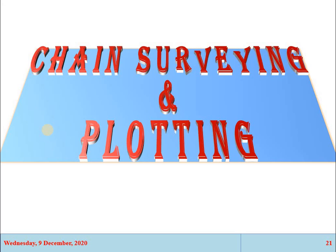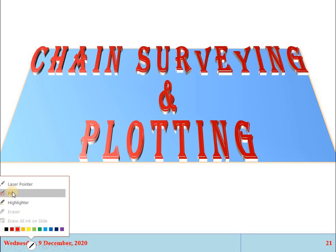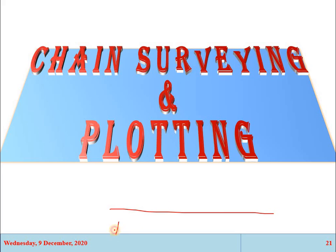In the previous lecture and in practical number 2, we properly discussed the measurement of linear distance with the help of a chain. First we do the ranging between the two end points of a specific line. Suppose this is point A and this is point B. First range the line, meaning place the ranging rods, and then we properly extend the chain to measure the distance between the two points. That was discussed in the previous lecture.